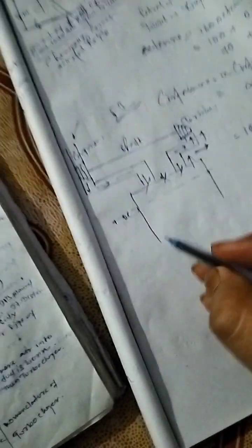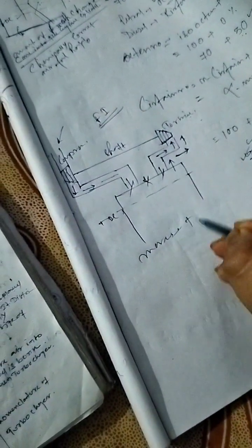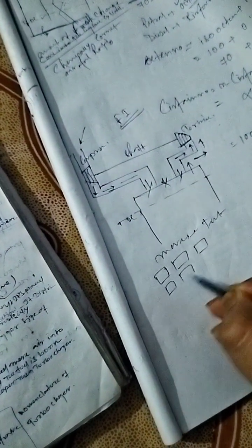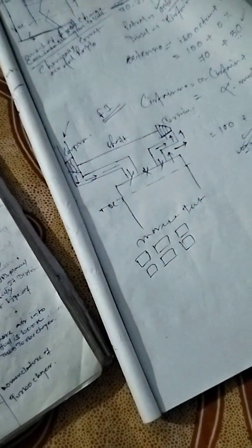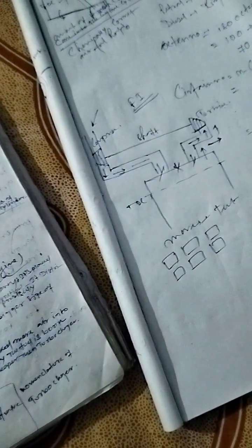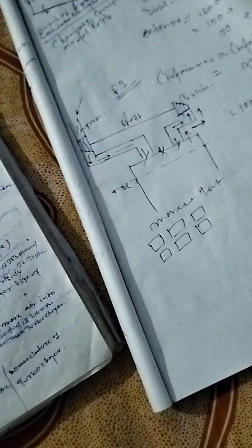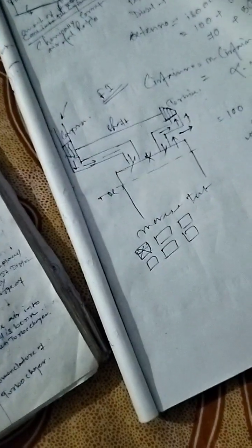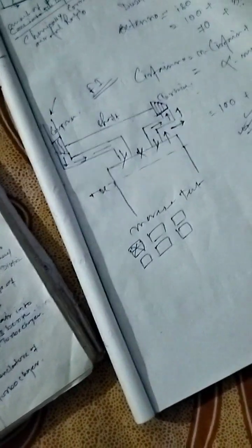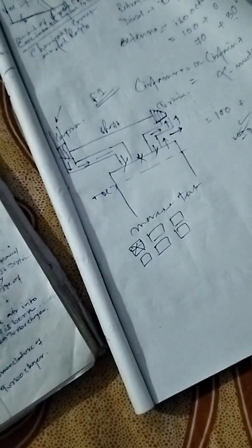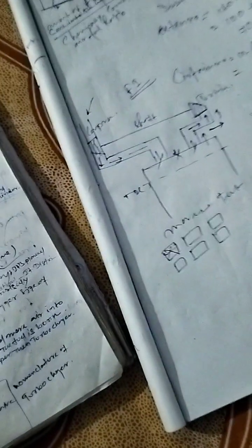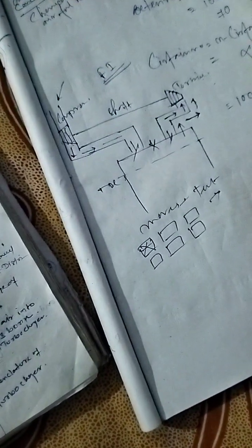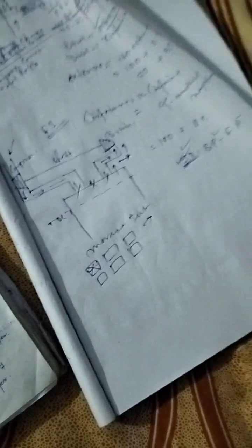To calculate the indicated power, we have a particular test, the Morse test. Here we have a multi-cylinder engine. In this diagram, we have a 6-cylinder engine. We run every cylinder at the same load and the same speed, and then we randomly choke one particular cylinder. Then there is definitely a loss in the speed, and we try to maintain the same speed and the same load again. This is how we calculate the indicated power.